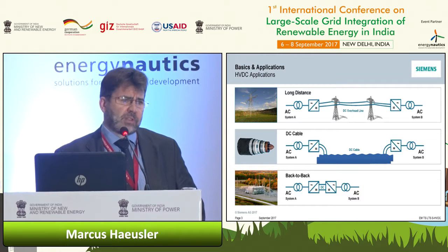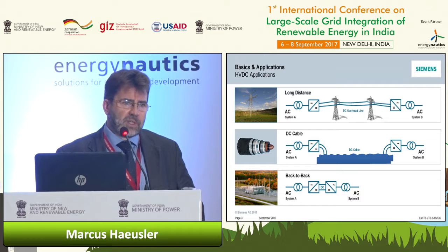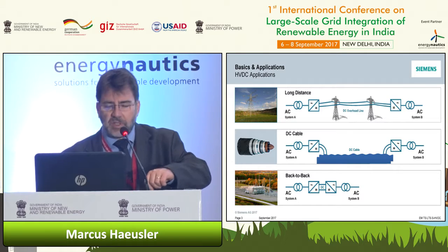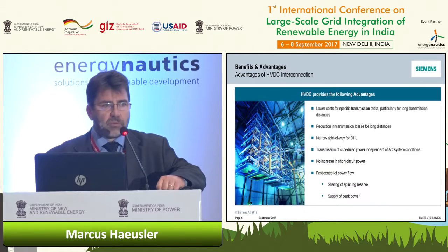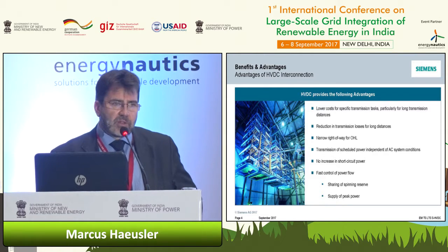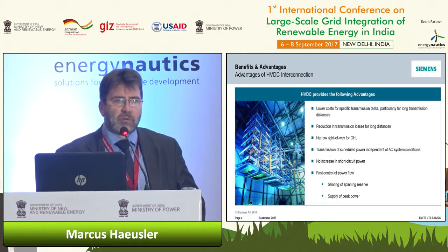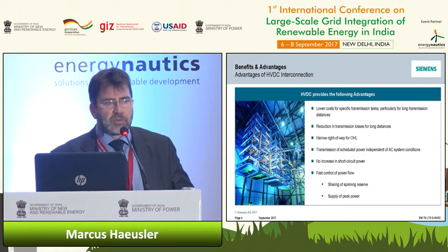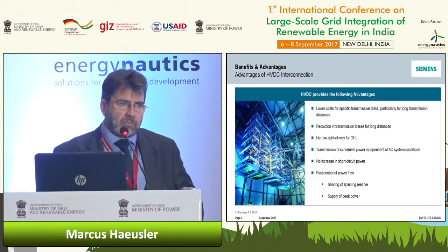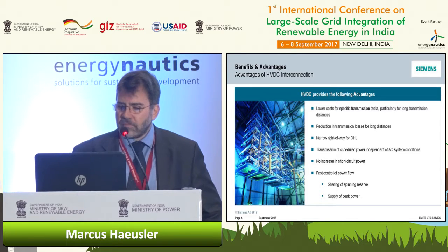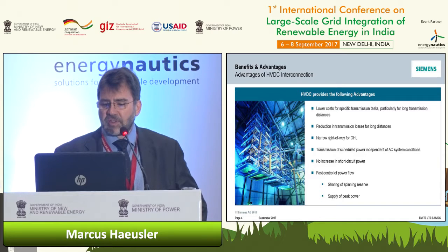And the last application is back-to-back links, which are used to connect different, not synchronized, AC systems and to exchange energy between both systems. So what is the reason why HVDC is used? HVDC is not replacing AC transmission, but it's complementing AC where AC is not so beneficial. Most important, in many projects HVDC is chosen because it's the most economic solution, especially if we talk about these long distances. It's just an economic decision in this case.